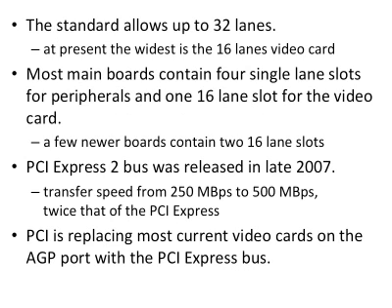The PCI Express standard allows up to 32 lanes, but most of the products available have 16 lanes. Most motherboards contain 4 single-lane slots for devices that do not require speeds over 250 megabytes per second. And for video cards, especially the high performance video cards with a graphics processor on them, they require 16 lanes per slot.